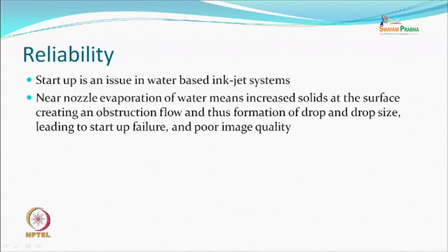And this happens because there is a near nozzle evaporation of water, which means solids at the surfaces are going to be deposited, and so it will cause an obstruction of flow, formation of a drop size, leading to a startup failure, and then of course poor image quality. So all of them are related. If you have a startup issue, that means ink is drying up at the nozzle.